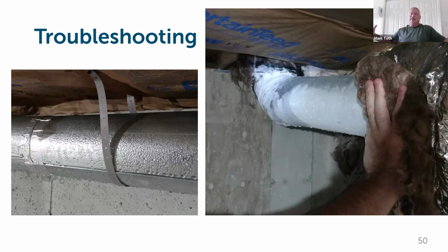So insulating it and allowing air to get in under the insulation, this can still happen, because what you're seeing here on the left is still happening. It's just freezing because the interior of the pipe is below freezing outside. So it has to be insulated, sealed on both ends, basically airtight, so that no air from that humid basement can get to it. And this will happen on any job where there is moisture in the house. So if it's a humid basement or humid crawl space, if it's not done properly, you will have a mess.